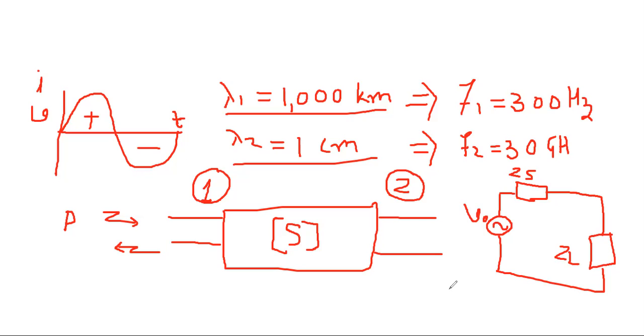So here, what does the maximum power transfer theorem say? Whatever the ZS is, it must be the complex conjugate of ZL, ZL star. Now what is this complex conjugate? It means that if your ZS is an impedance, impedance is represented in terms of resistance, maybe your RS, and reactance. Reactance is represented as JX, so I will represent ZS as RS plus JXS.